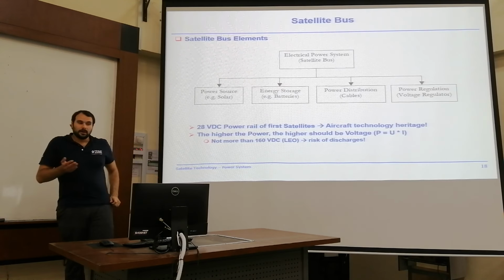And just to let you know, I again show you a real-life example of a power bus. This is part of the power bus of the Flying Laptop satellite, the small satellite. Down here we see the unregulated bus, 70 volts. So this is directly coming from our batteries. And then we have a lot of interfaces there, interfacing all the different units you can think of. We have some heaters that are fed by 12 volts.